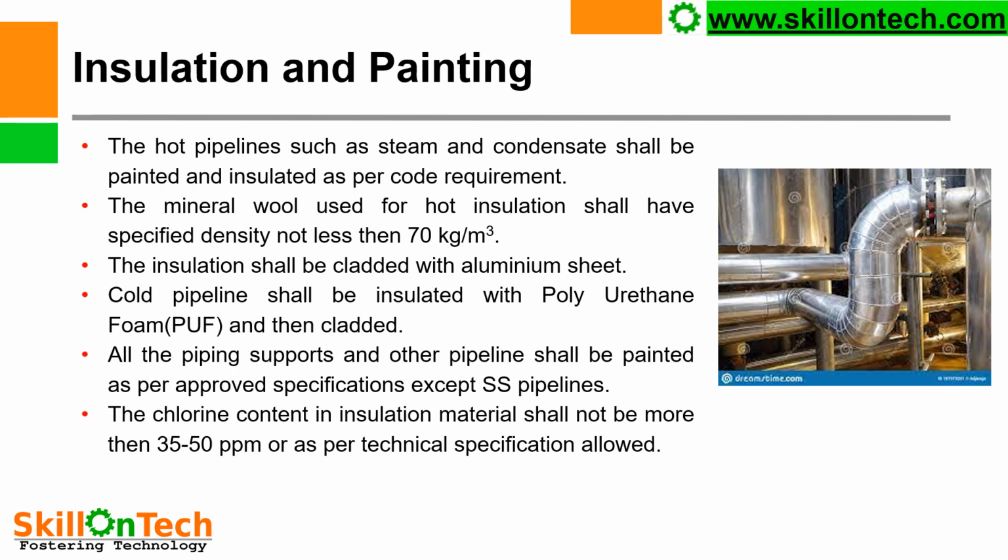All the piping supports and other pipelines shall be painted as per approved specification except SS pipelines. The chlorine content in insulation material shall not be more than 35 to 50 ppm or as per technical specification allowed.